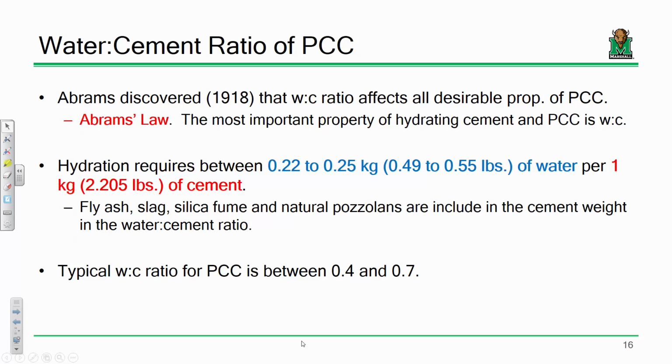So for instance, a concrete mix design for, let's say, a bridge pier in Miami that's going to be subjected to seawater and a lot of salt content is going to have a different mix proportion than, let's say, an internal floor slab in a building that's not going to be subjected to any deleterious environmental impacts. That concrete mix is going to be different than the previous. So we're going to take its target compressive strength, its intended use, and data associated with the ingredients, like the specific gravity of the coarse aggregate and fine aggregate and so on and so forth.